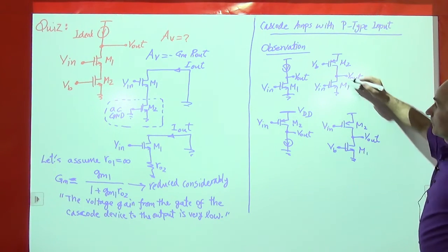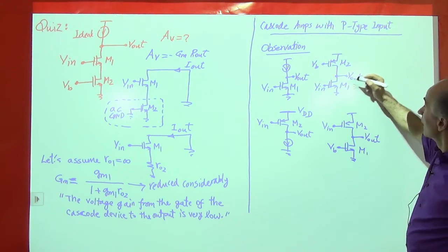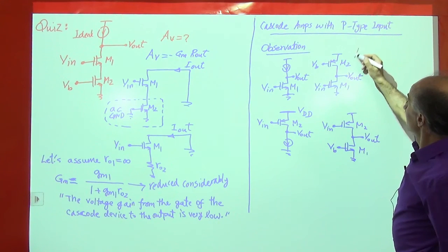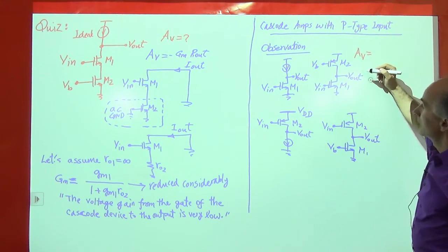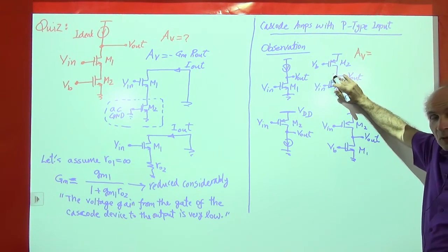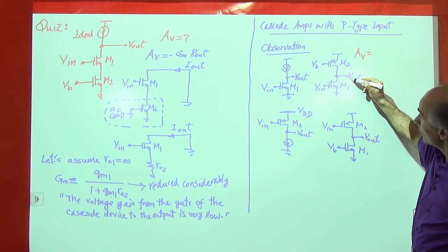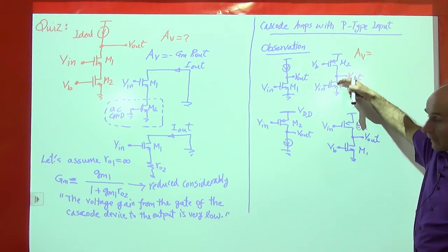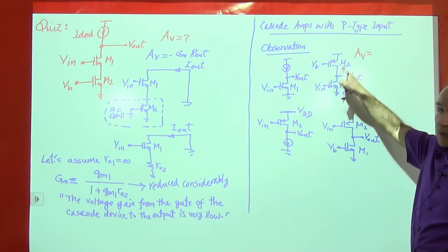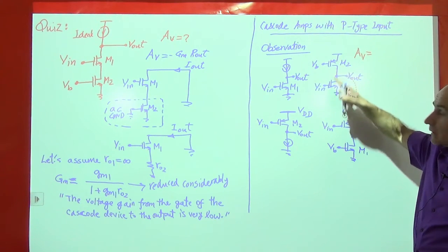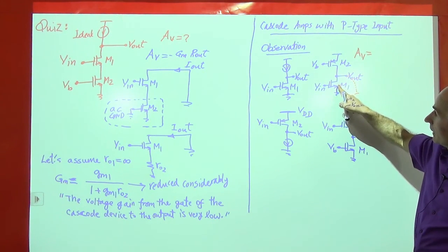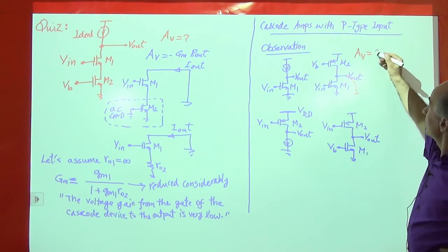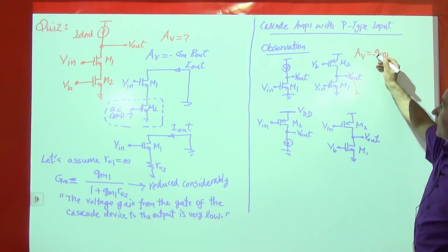All right. How much is the voltage gain of the circuit? Okay, so remember this expression here? Again, it comes in handy. So I will write AV equals the transconductance of the circuit. So again, in your mind, place a short circuit to AC ground and see how much current flows through this in the small signal model. This guy is out of the picture. Okay, doesn't produce any current, it's out. So what we have is a current flowing here, which is given by GM1 times V in. So that's GM1 with a negative sign.